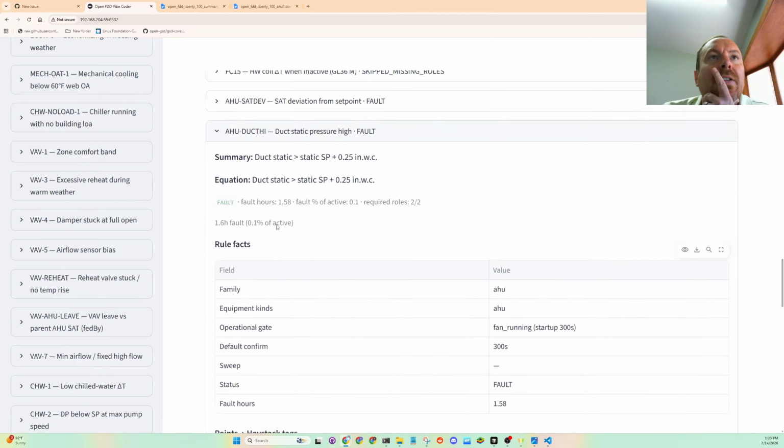Look at that. So I'll just zoom in on a day right here, and it looks to me that all night long, this air handling unit is running in hand, and then it takes off in the morning. Hopefully, you guys are seeing this too.